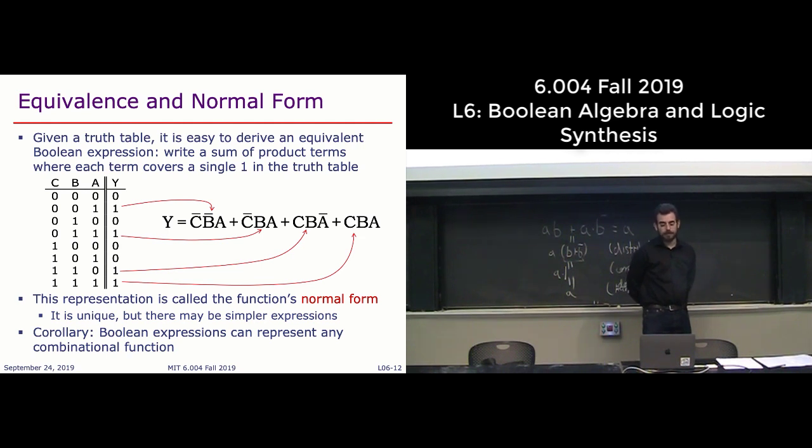Well, you have a term here that says it's the AND of 3 different variables, right? And so you're ANDing not C and not B, which are both 1, and then ANDing them with A, which is also 1. So 1 and 1 and 1 is 1, and so you have a 1 there, and 0 elsewhere, because no other combination of inputs will cause that product term to become a 1.